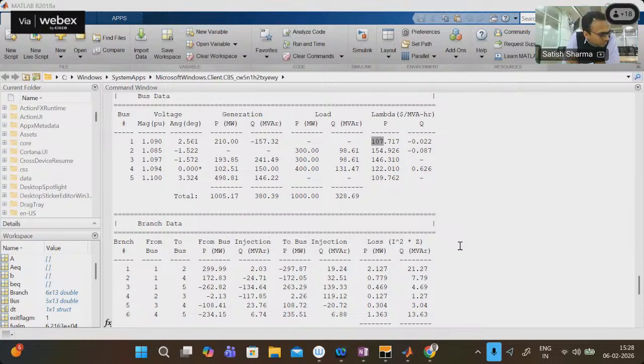Yes. Another thing is how to include differential variables. What do you mean by differential variables? What exactly is your meaning? Equations that represent the dynamics of synchronous generators, like the swing equations. Here, the change in electrical power and load will evolve with respect to time, like delta will evolve with respect to time. So that is represented in terms of differential equations. I studied some papers where differential algebraic problems are being considered. So, in those papers, were differential equations included in optimization as well?